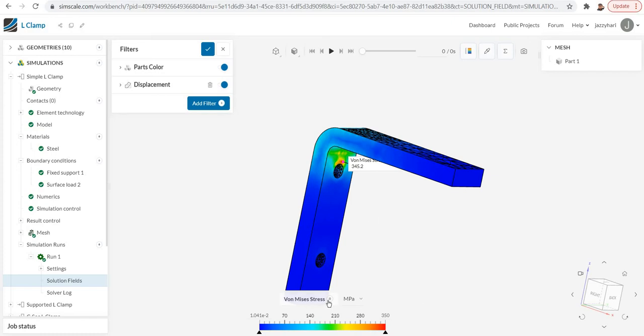Okay, so we will now check what the rigidity, the displacement magnitude, would be. We can go directly to the displacement magnitude, and it is already in mm. It is 5.59 e raised to -1, so that will be 0.5. That is almost 0.5 mm. So 500 microns, almost 500 microns displacement is there. You can see the design is not rigid also.